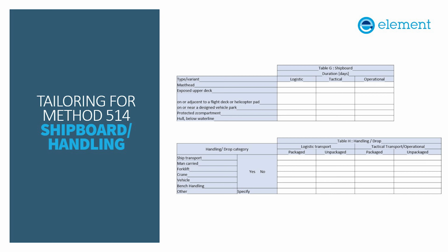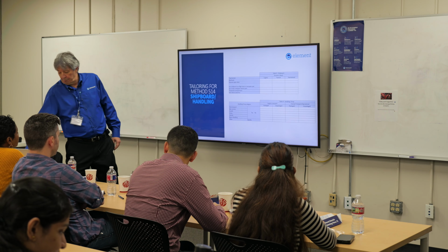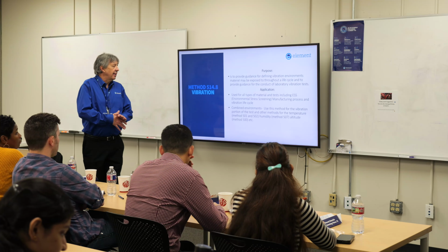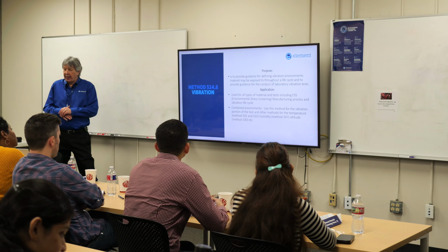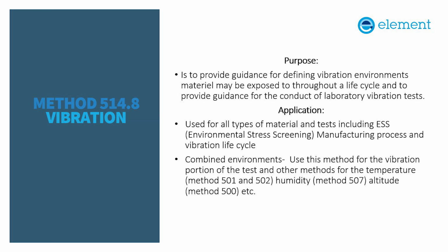Handling, drop, is it going to be man carried? Is it going to be slung underneath the helicopter? However else, can it be dropped? Is it two-man carry? All of this you're going to have to figure out. And the purpose, obviously, for this 810 is to provide guidelines for defining vibration environment materials can be exposed to throughout its life cycle.